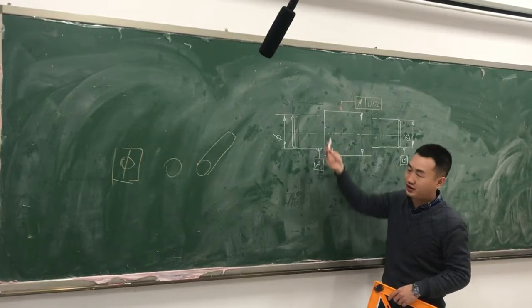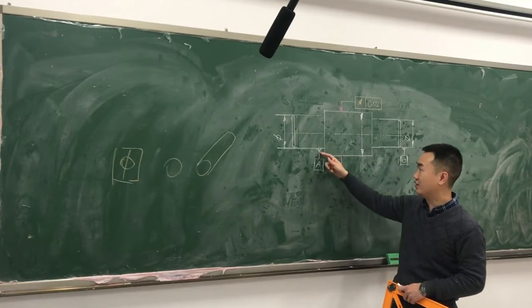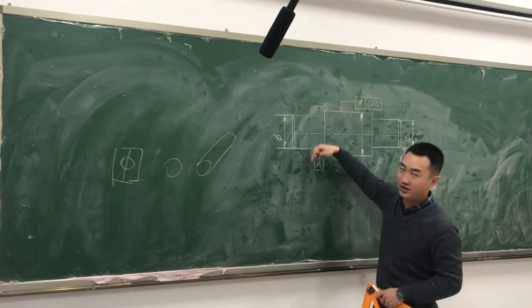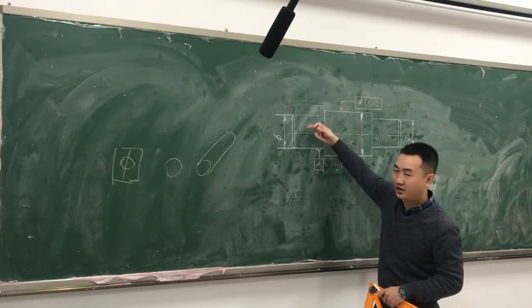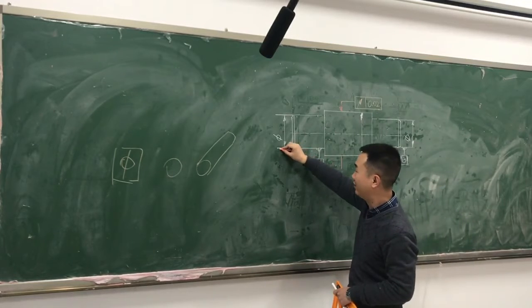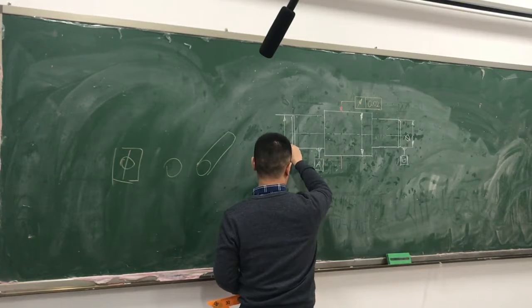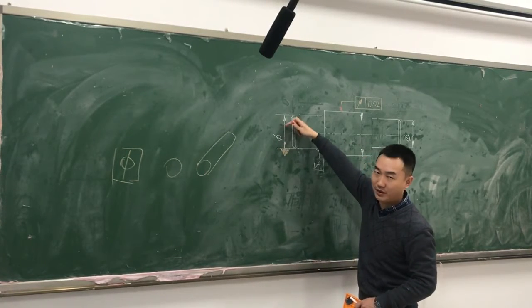The surface of a cylinder can never be a datum in a real case, so it's wrong. And the datum, in fact, should be the axis of the cylinder, right? If we want to say datum A is the axis of this cylinder, where should I place it? I should place datum A here, as an extension of this dimension line.